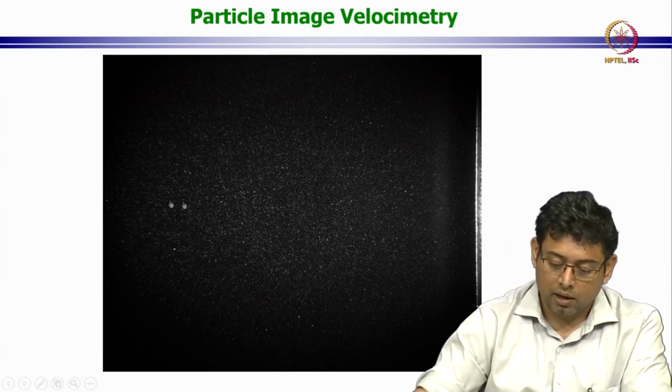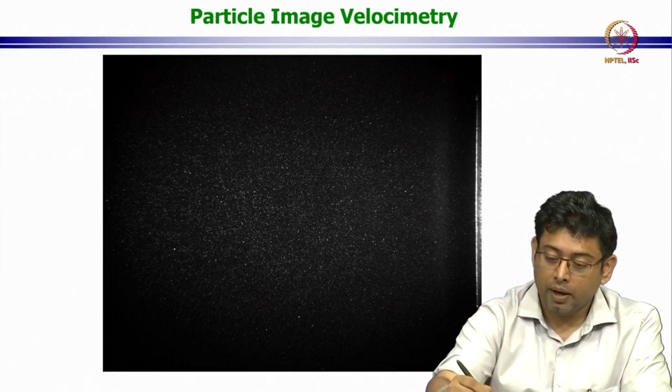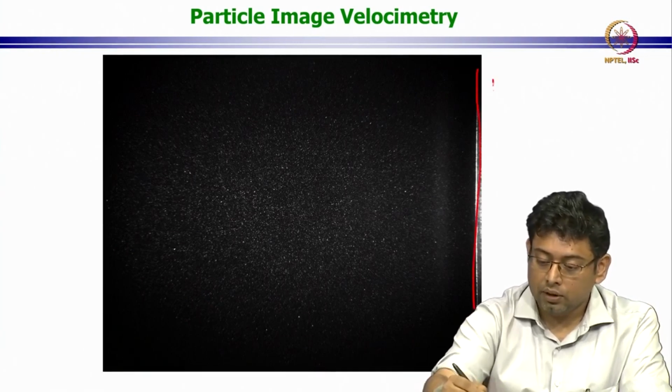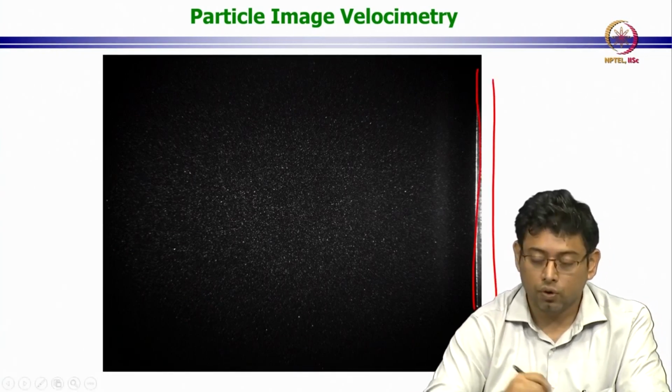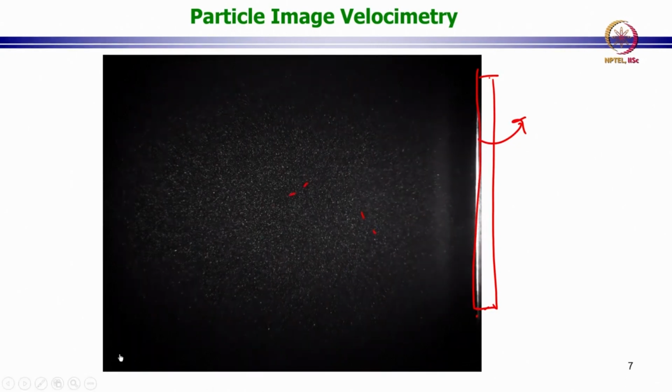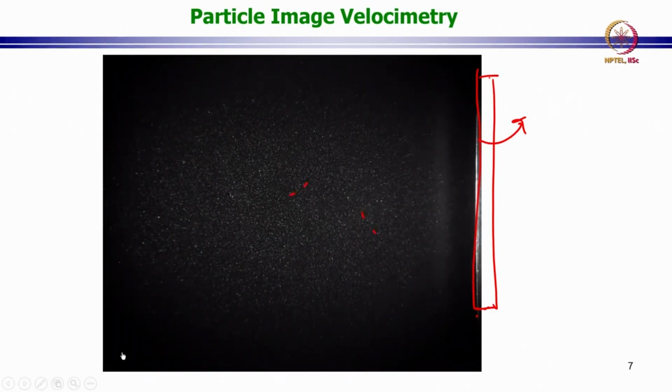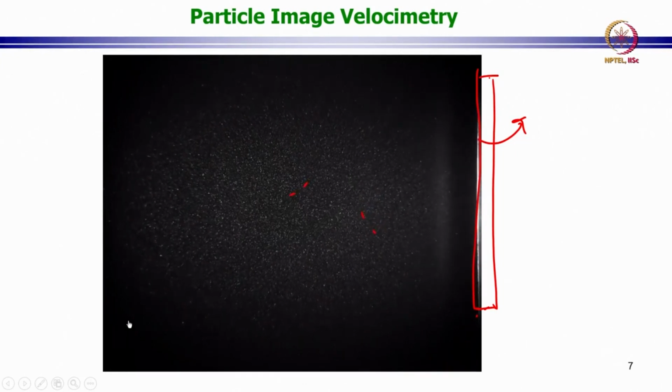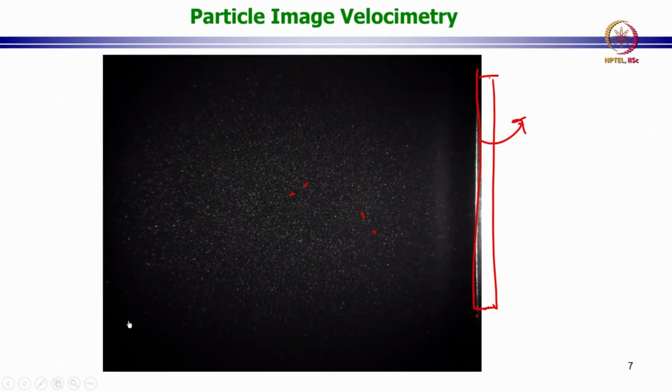And here, for example, this is a slightly different example from what he's going to show you, but in this case this is also a particle image velocimetry analysis where there is a rotating rod and there are glass spheres suspended in the flow, and they are being captured through a high speed camera. So, we did not use a normal PIV camera, but we just used high speed imaging, and we were able to get slow enough changes between successive frames so that our analysis can be done.